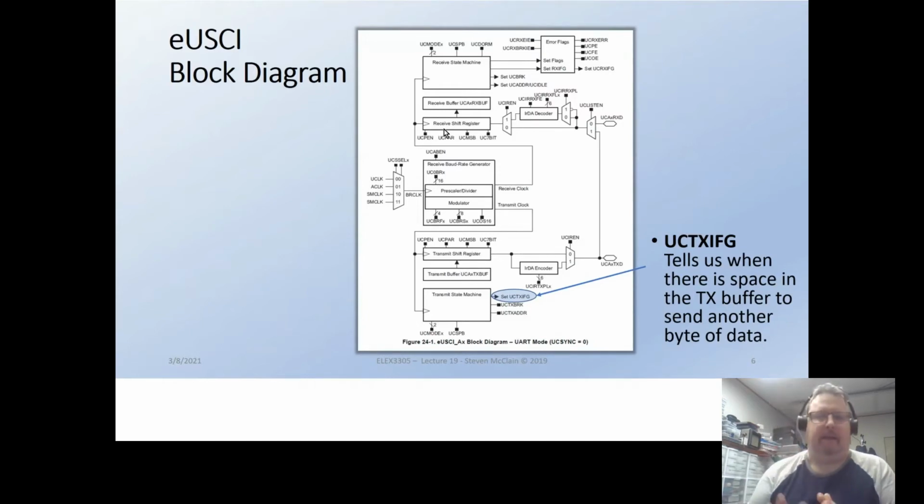But the dance with the flags and dropping the bytes in and out of the registers has to happen either in main in a busy loop or under interrupt, or DMA does the same thing, only in hardware.